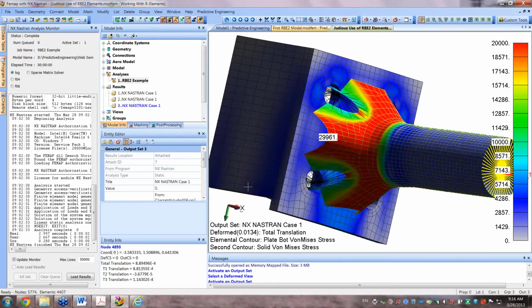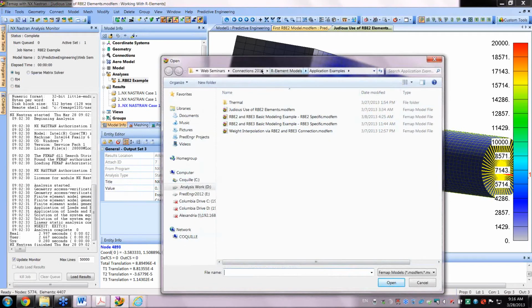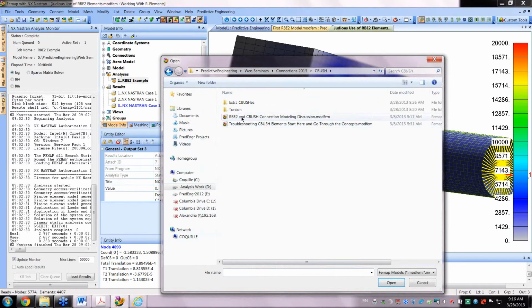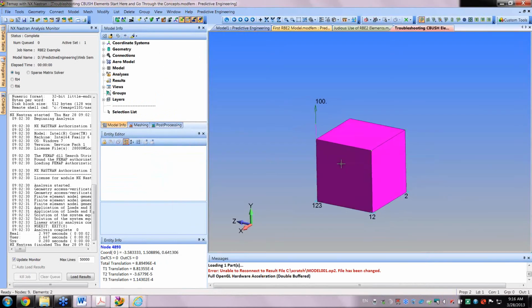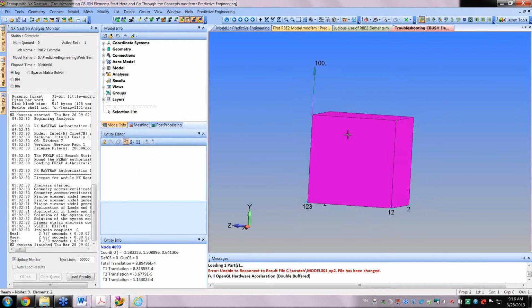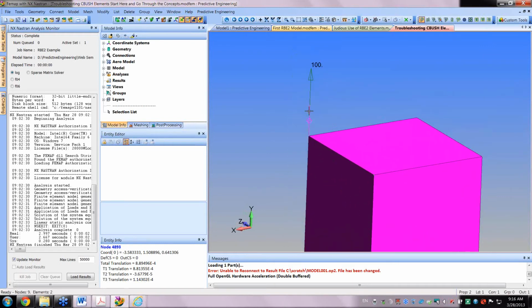Since we're getting up to an hour, I want to get straight to my little example of why the CBUSH sometimes drives people a little bit crazy trying to figure it out. Okay, here's my CBUSH, 6 DOF element. Well, look, we've got a solid element that has 3 DOF on it. Okay, in this little example, of course, tailored, we're going to pull up properties.